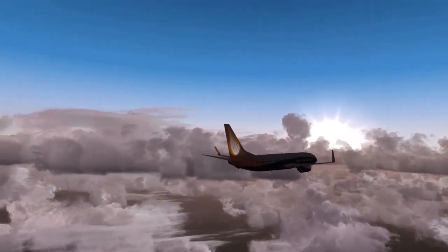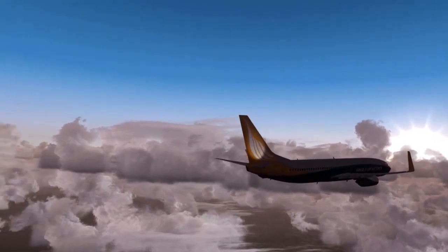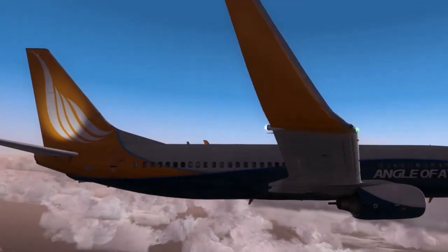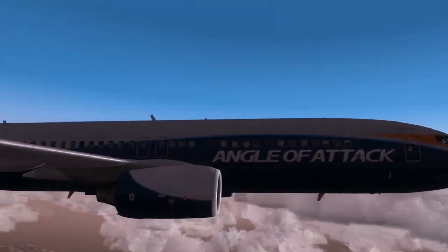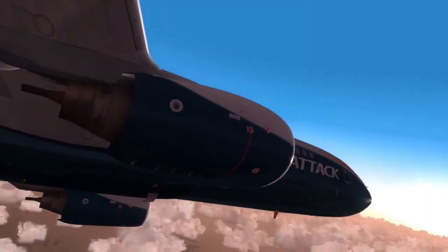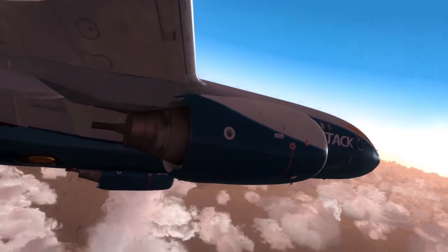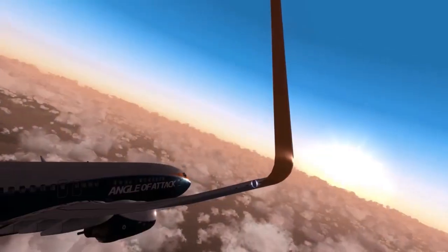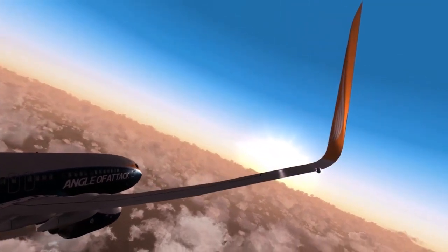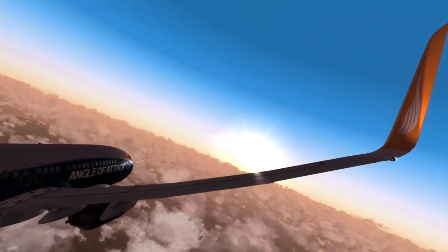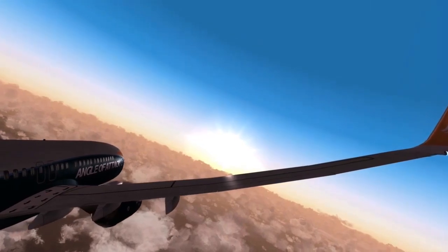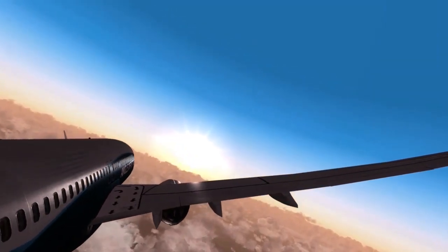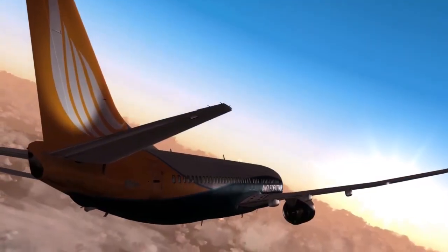Our discussion about the engine's bleed air system assumed that both engines were up and running under normal conditions. However, what happens during flight phases where bleed air is required but engines are turned off and engine bleed air is unavailable? As we mentioned before, two more sources of bleed air are available. Neither of them is as important and fundamental as the engine bleed air system, yet both may perform most of the functions to supply aircraft bleed air demand.